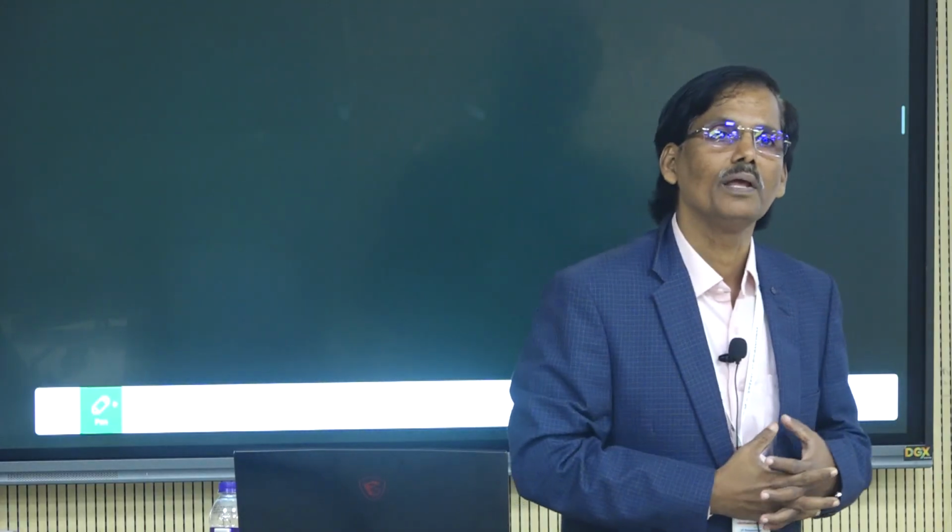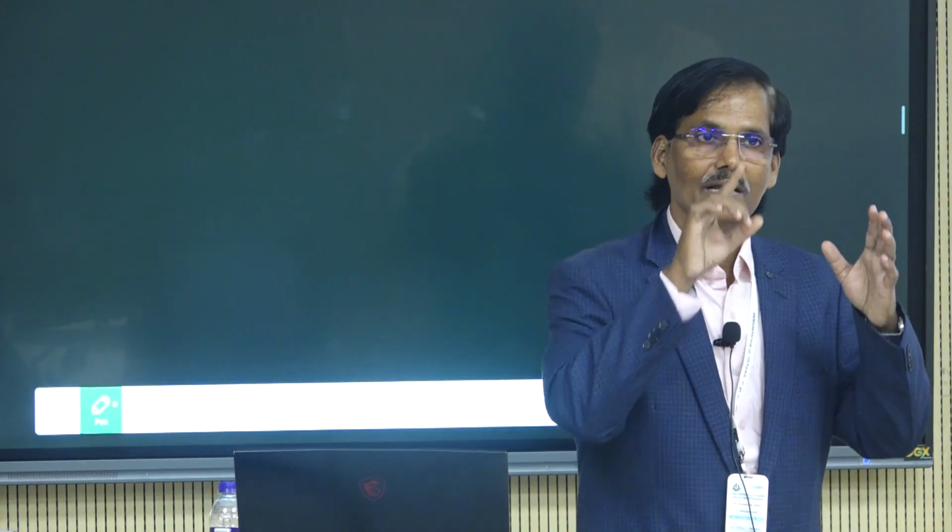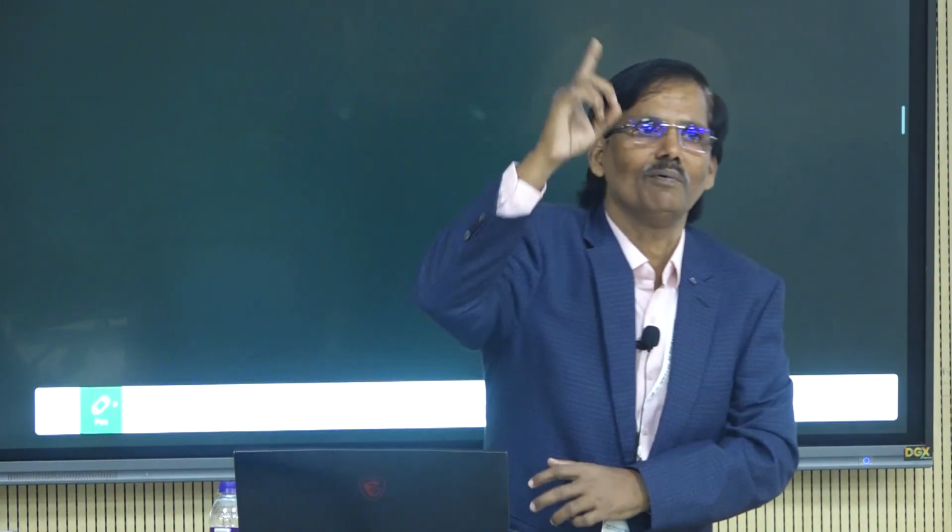Now the question comes, out of these two terms, del upon del x and del upon del y, which one is more important? You have to think of. Del x. Because the del x term is the boundary layer, right? Which is very small. 1 upon very small is a big quantity. So that is more important compared to del upon del y. So here you can neglect del square T upon del y square in comparison to your del square T upon del x square.